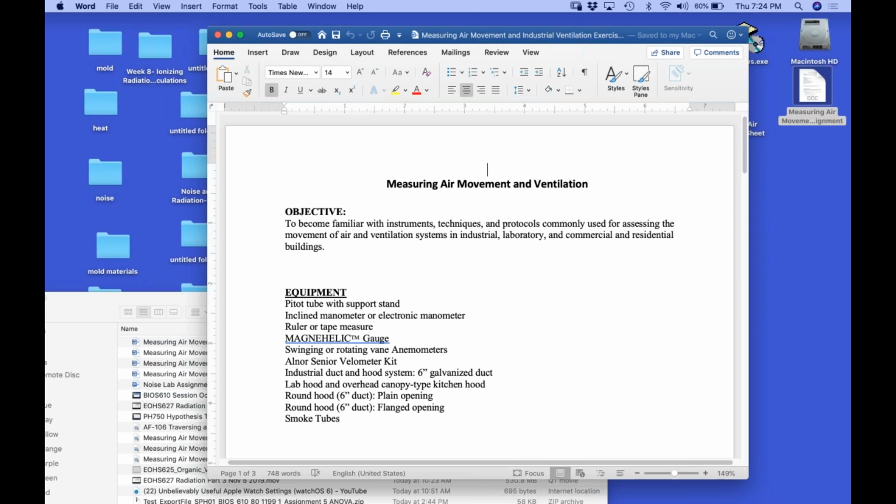Right? So now, we're going to take 6 readings. Now, normally, what I would do is, remember that chart that I have down? That's the 6-inch ductwork, where the first reading has to be 0.035 times 6 inches, whatever it is. Write that amount in. Really what you should be doing is converting that into inches and then marking this. You may notice that there are markings on here from a previous reading.